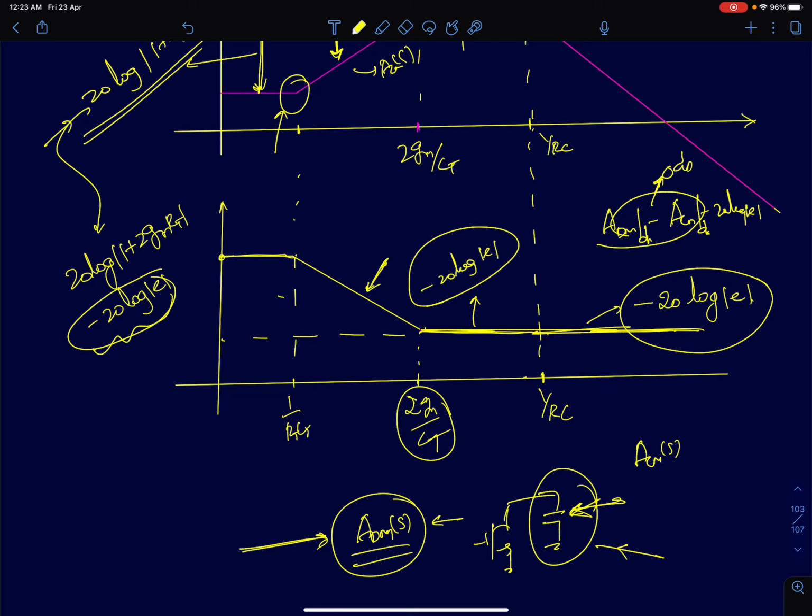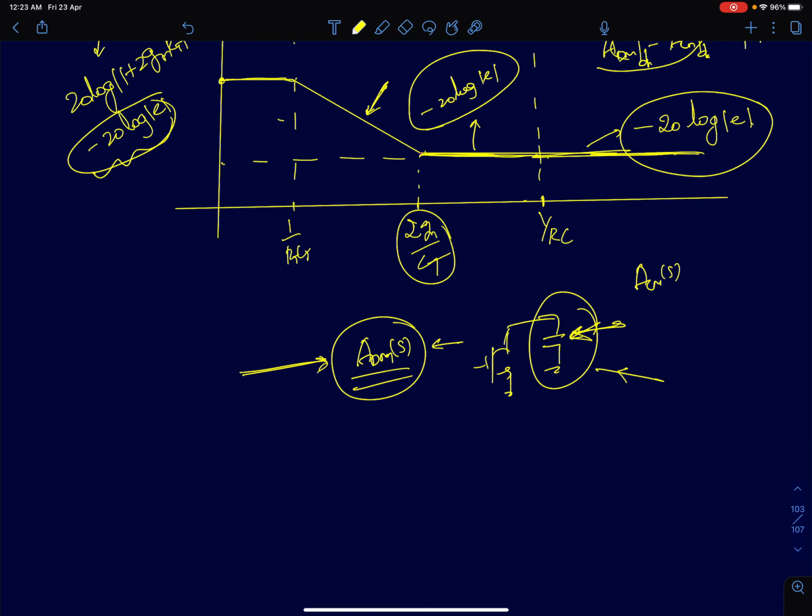And that makes intuitive sense because of this output capacitance, you are going to get a pole in ADM. You will get the same pole in ACM as well, because you are taking the output at the same terminal. This capacitance is with respect to ground. So in this circuit, you will get the same pole. Therefore, both the poles will cancel out.